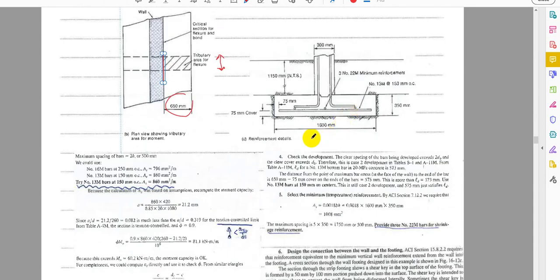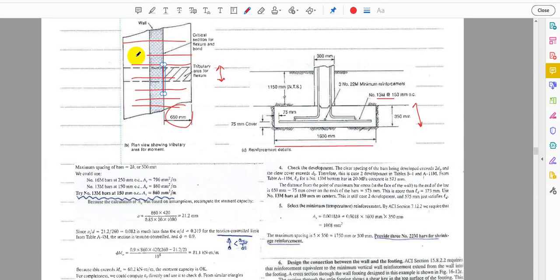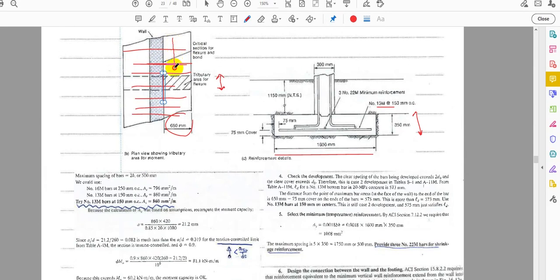And this is the summary, right? We have assumed, and now we calculate 1,600 millimeters, and with the depth increased, revised to 350, and we have a rebar, and this rebar goes one way right now. Okay, one way slab, and we may have to select another longitudinal rebar for temperature and for nonstructural reasons. Look at that right there.